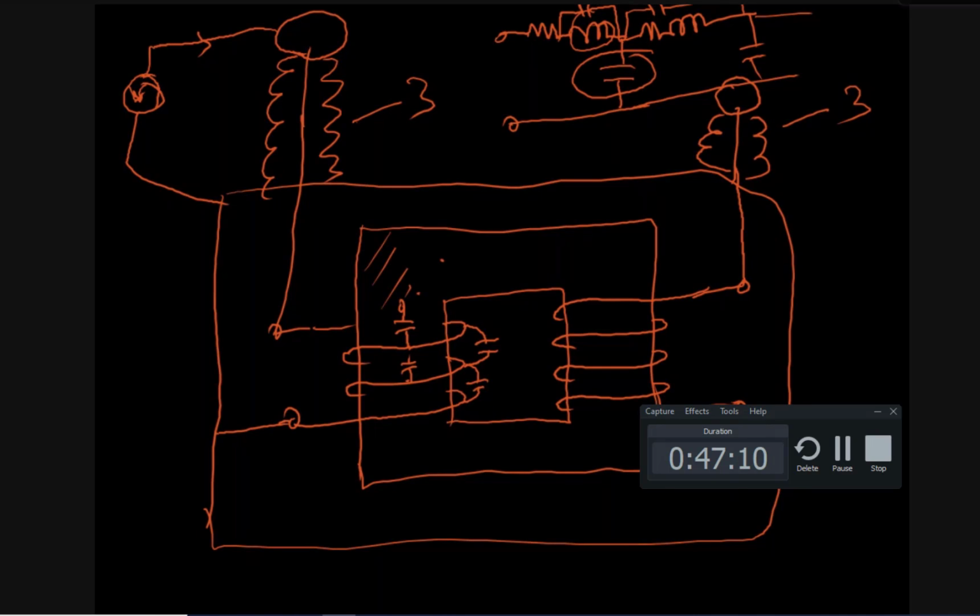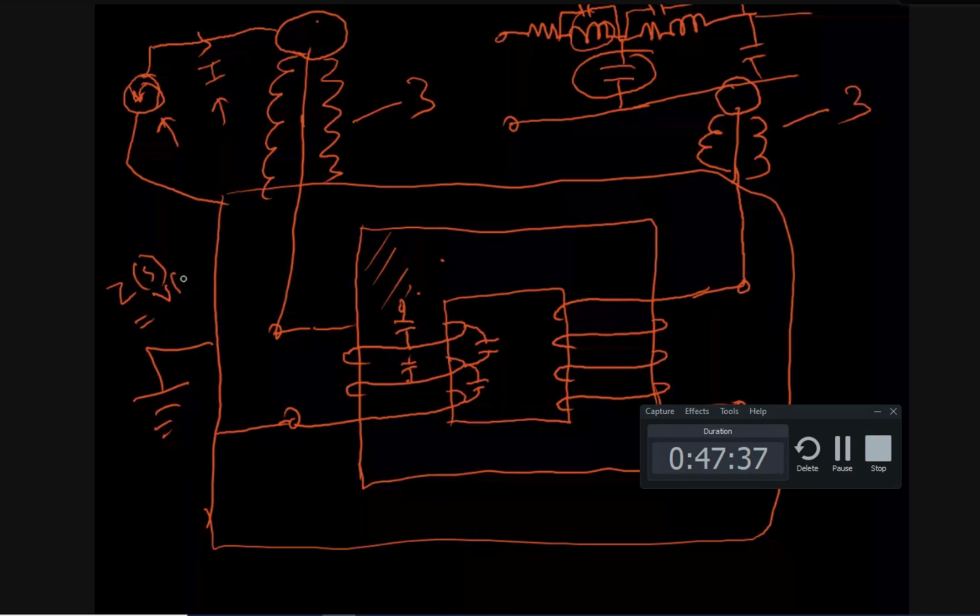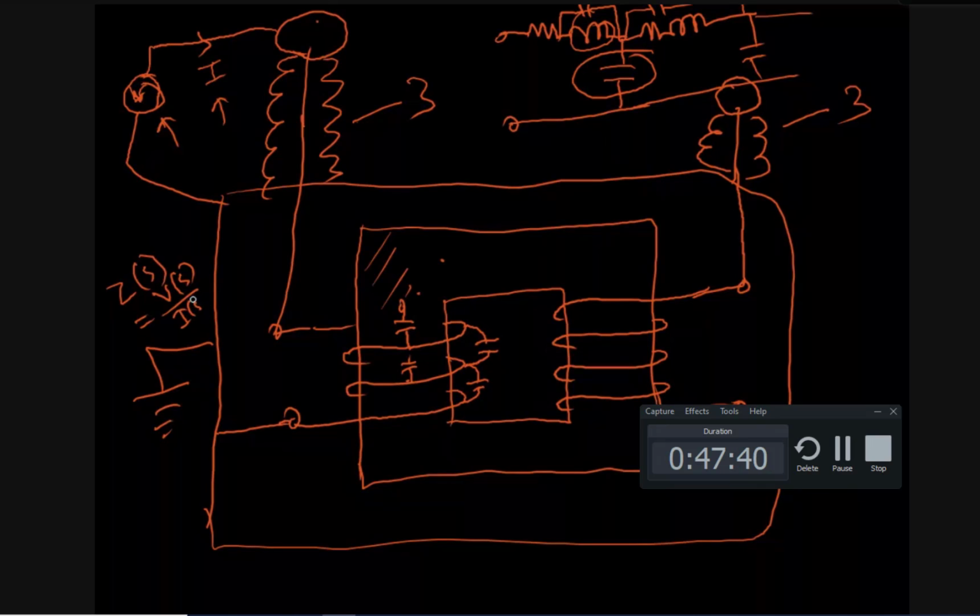The transformer tank is at ground potential, and one of the terminals is at high potential, and then I am finding out the current. Now I know the voltage, I know the current, I know the impedance function Z of S. This is the input impedance function. Of course, there are several combinations of impedances here, transfer impedance, etc. I am simply saying V of S by I of S, I can find it out. In the frequency domain, I can analyze where zeros are there, where poles are there. And then from this, synthesizing a network can be done.